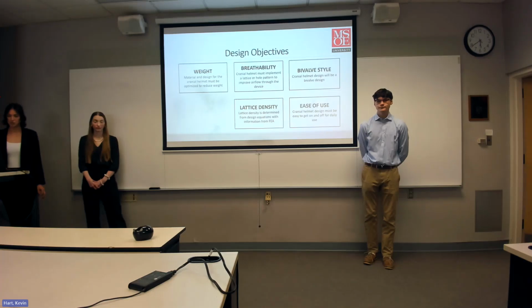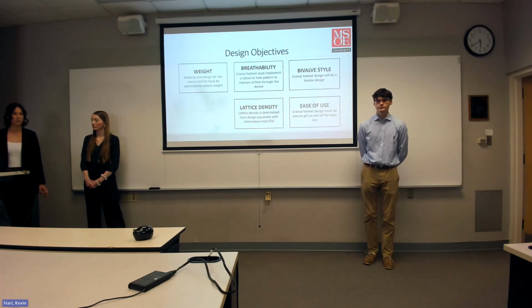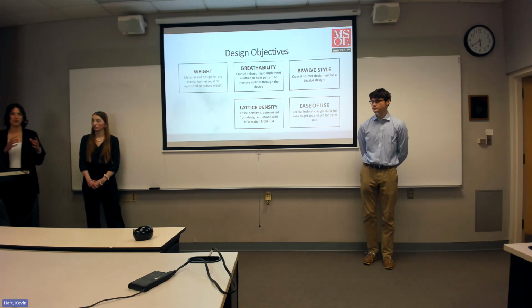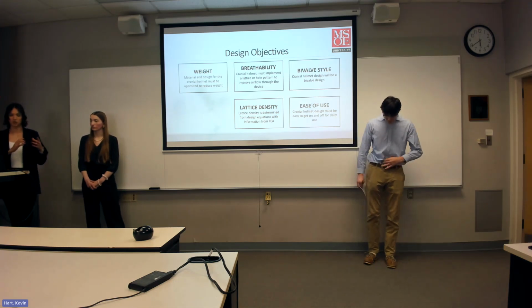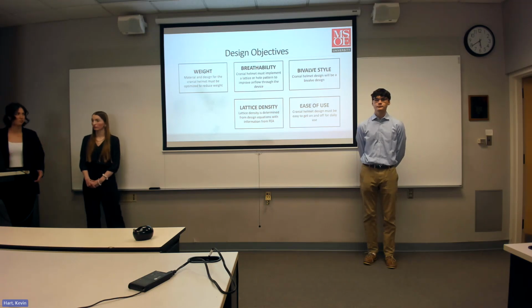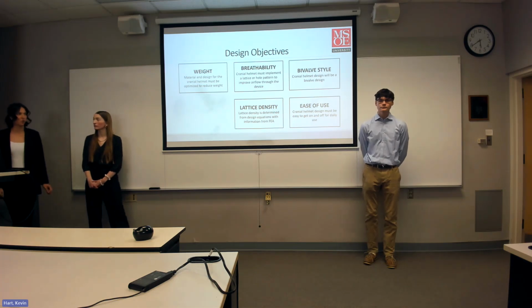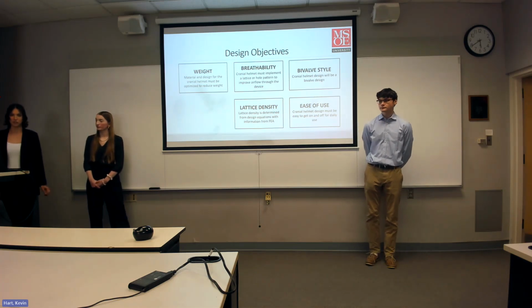The lattice density was also a concern, and this is informed by FEA results, but basically this just means how dense the lattice cells are. So objectively, less dense lattice is more spread out, and more dense lattice is more condensed. And that is just informed by FEA, and basically our goal with that is to maintain the structural integrity of the helmet while also maintaining breathability.